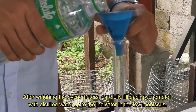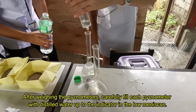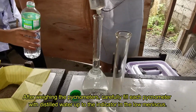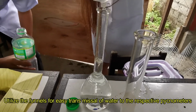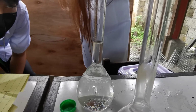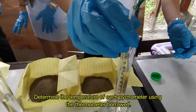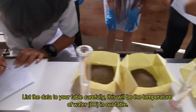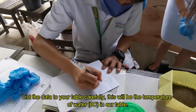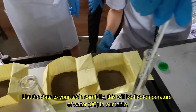After weighing the pycnometers, carefully fill each pycnometer with distilled water up to the indicator at the lower meniscus. Utilize the funnels for easy transfer of water to the respective pycnometers. Determine the temperature of each pycnometer using the thermometer borrowed. List the data in your table carefully. This will be the temperature of water in degrees Celsius in our table.